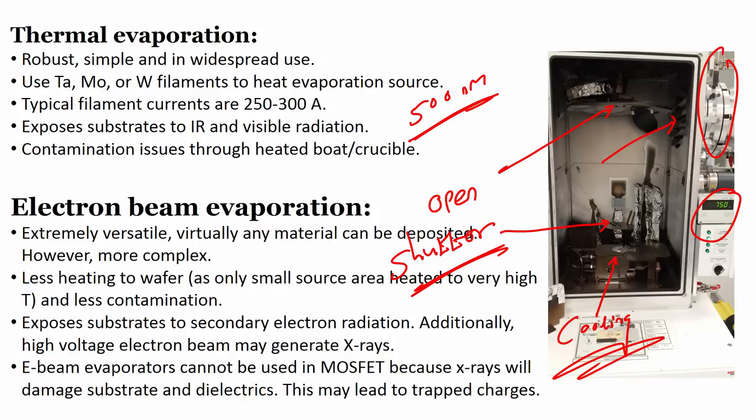There is a crystal over here which is called a quartz crystal microbalance, used to understand how much deposition has been done. Quartz has a property which is called the piezoelectric property. That means, when we apply pressure, there is a change in voltage. We can use this property to understand the thickness of the film, and we can program the system such that when the desired film thickness is reached, the shutter will get closed. So, QCM is an extremely important tool used within the e-beam evaporator or PVD in general, to understand how much thickness of the film has been deposited.